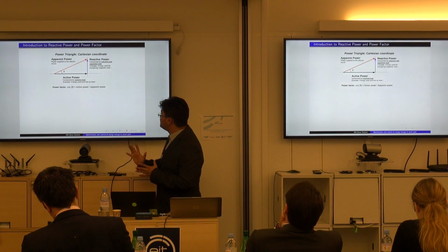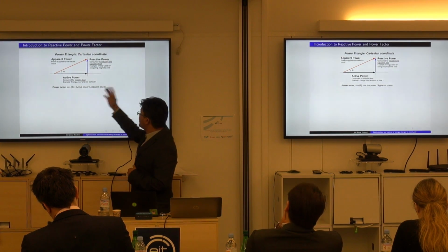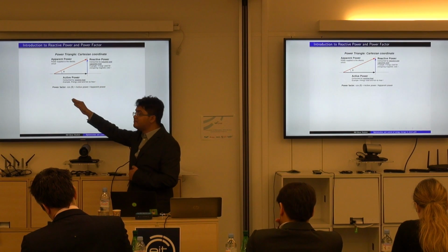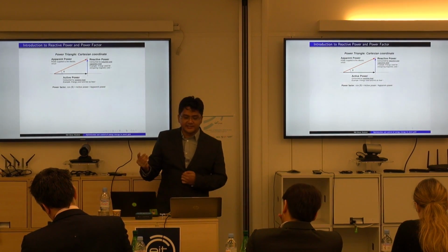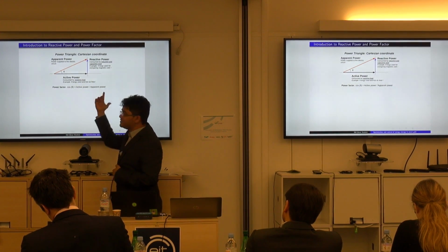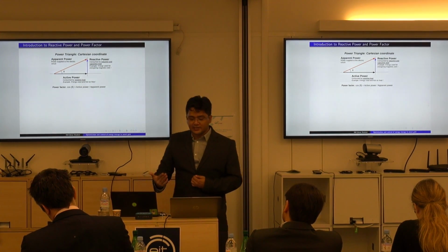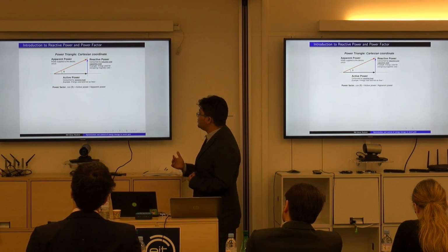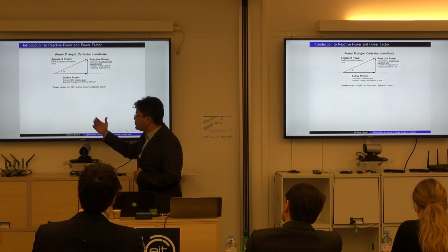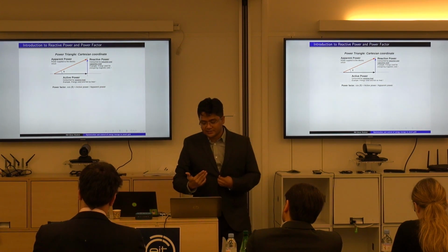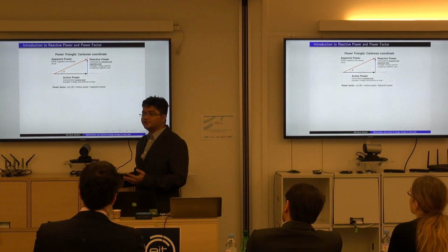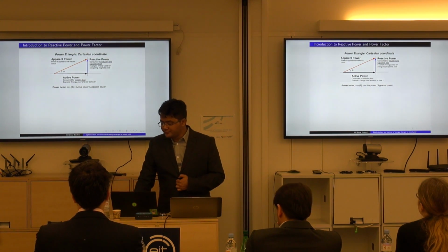So active and reactive power in Cartesian coordinates can be represented like something like this. And the angle between apparent power and active power is the power factor angle. And if you take the cos, which is the ratio of active and apparent power, is a typical indicator of one of the indicators of power quality. And as power factor degrades, then what we observe is the losses will increase, the ability to transfer active power over the network reduces, which we can see here.